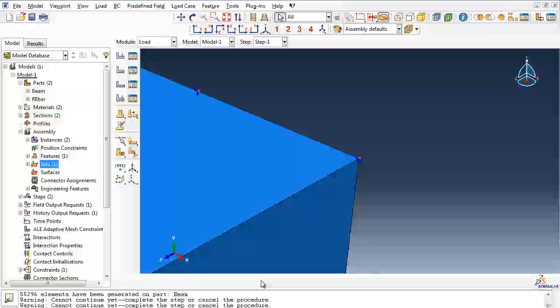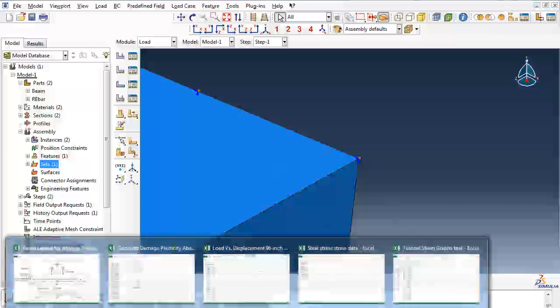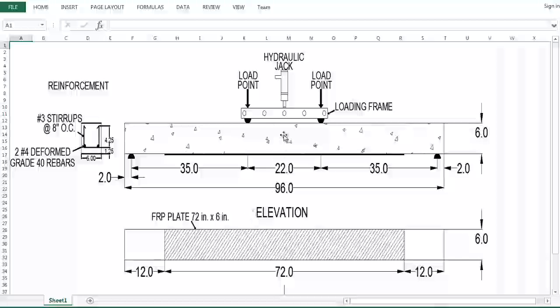The deflection on our real beam was measured at midspan with a height gauge right around here, so I don't think it matters if we go into the page a little bit, because the displacement is going to be taken from this horizontal datum down this way, so we're okay.